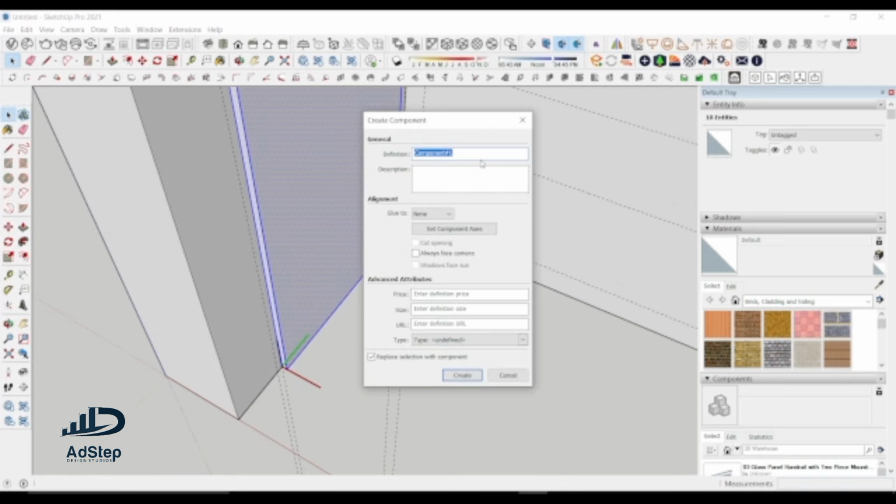I've done a video of how to name a component in my previous video. You can check this YouTube channel to see how to name a component properly. For this wardrobe, I'm going to name the first one WR01, that is the code, dash the side, standing, aspect is 42, standing, board type HDF, thickness 15 mm, edge binding.